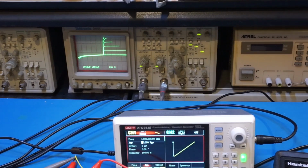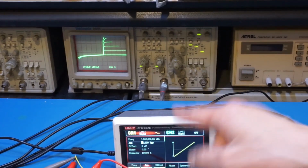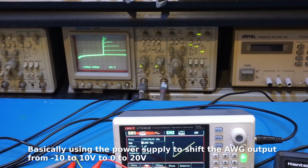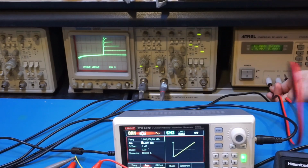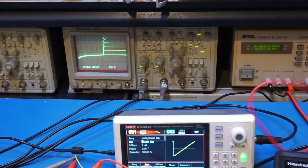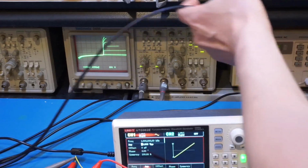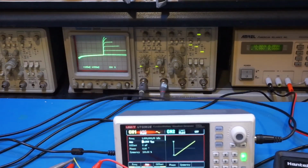But the problem right now is we cannot utilize the negative 10 volts. So to utilize that, what I'm going to do is to add a DC offset to this signal here. So for that, I'm going to turn on the power supply and generate 10 volts, which is what is currently outputting. And I'm going to put it on top of this output from the signal generator here.